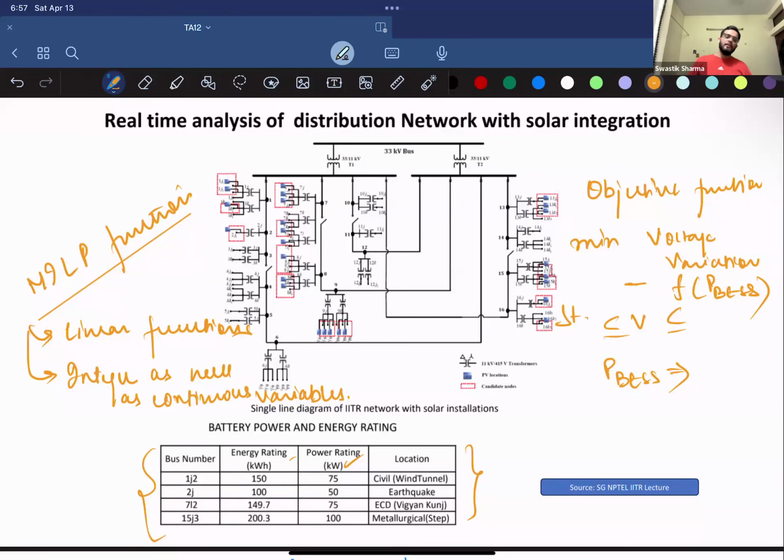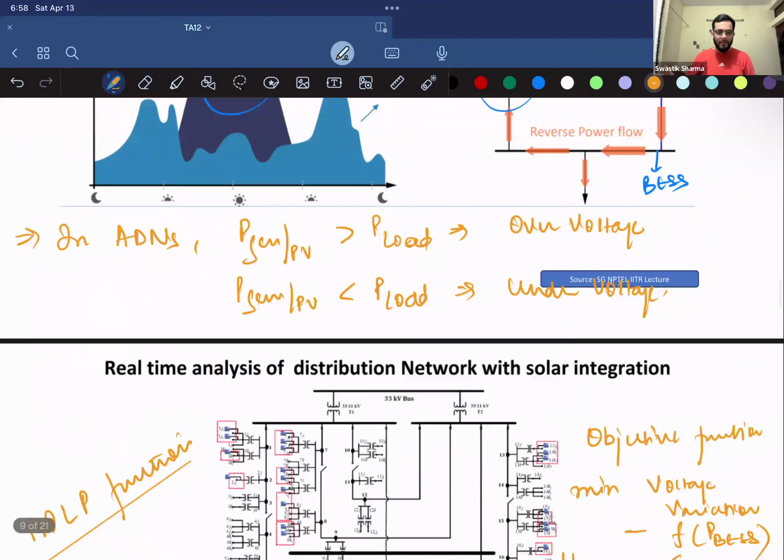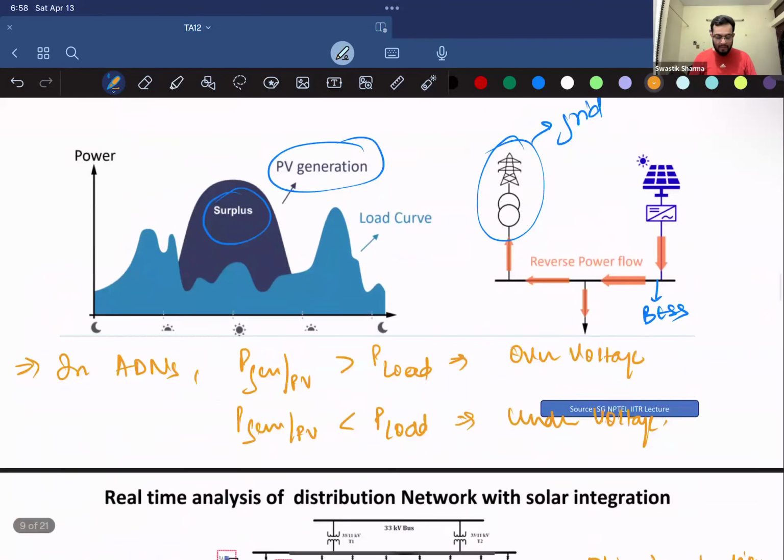So this is the benefit of your PHIL, right? Instead of just going into the field and installing components here and there without a worry of how your system would react to unconstrained or violating situations, you can simulate it on an RTDS platform or a real time simulator, so that all of your worries could be vanished before you install it on a field pilot or a real life scenario.